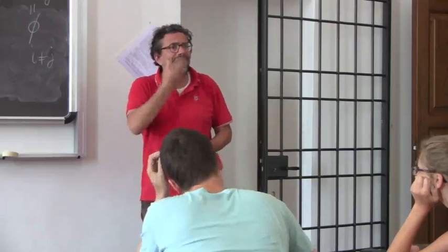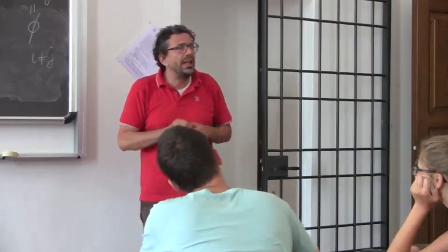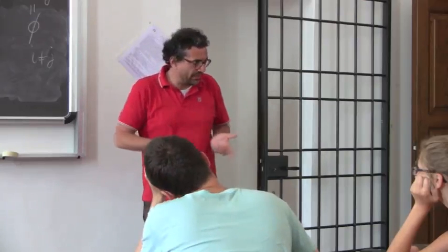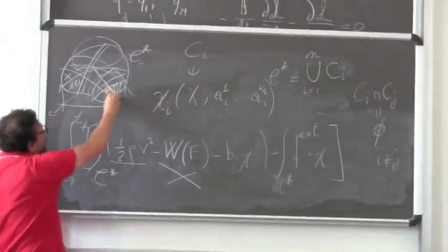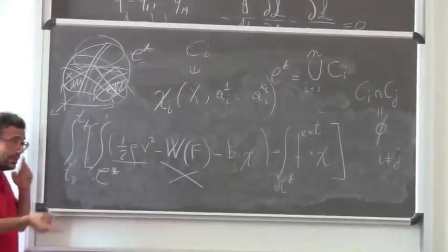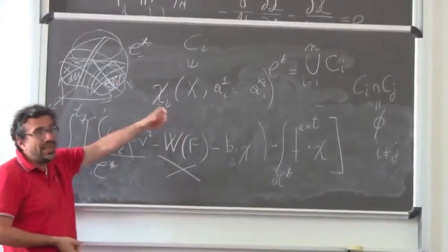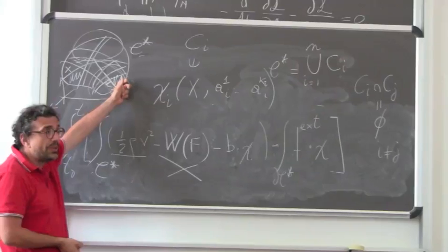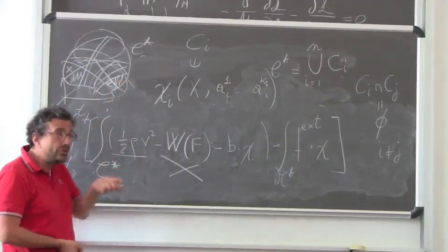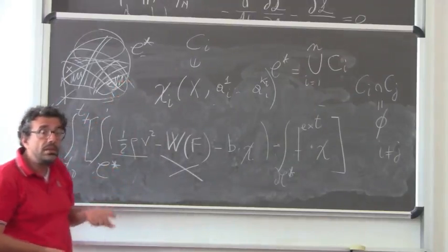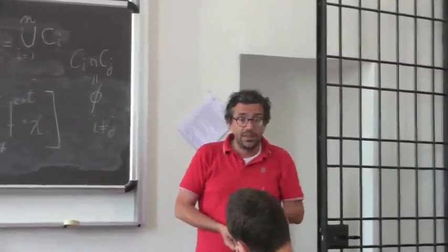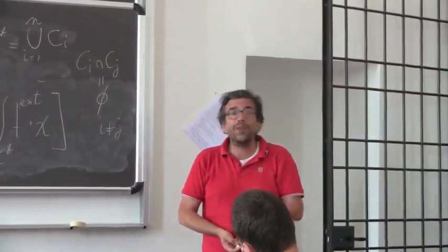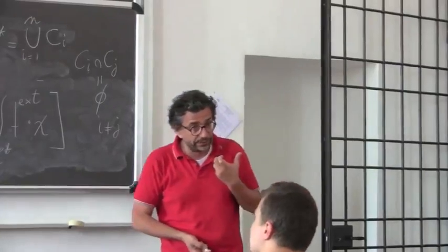So if your finite elements are chosen in a bad way, not a wise way, so that in this element you have a displacement, in this other element you have another displacement, and you get a discontinuity, you are in trouble, because your tentative solution is not respecting the kinematic assumptions you have accepted at the beginning of all the story.